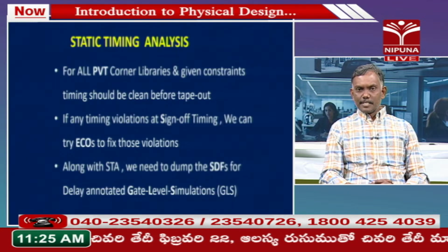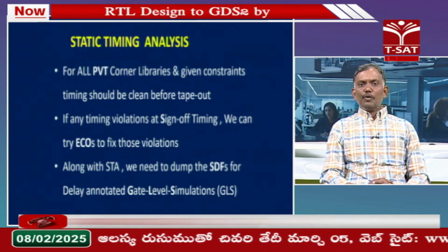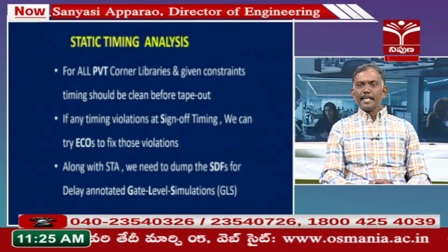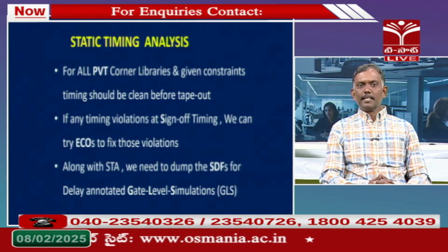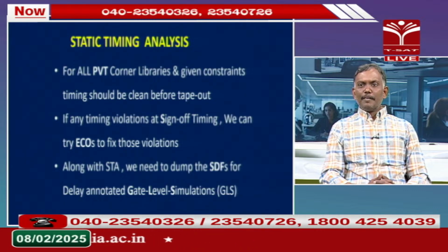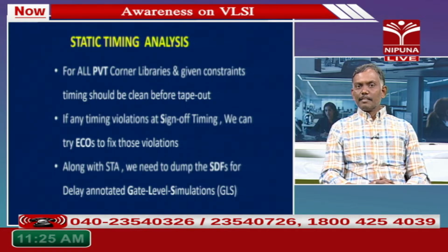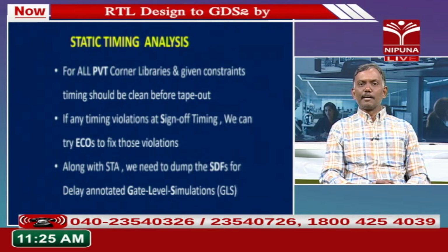Static timing analysis is a part of sign off. We should do the setup check and hold check for all PVT corner libraries. You have the 3 PVT corners we discussed so far: slow corner, typical corner, fast corner. For all PVT corners and the given constraint file we discussed as a part of logic synthesis and PNR, we should check setup and hold as a part of this static timing analysis.